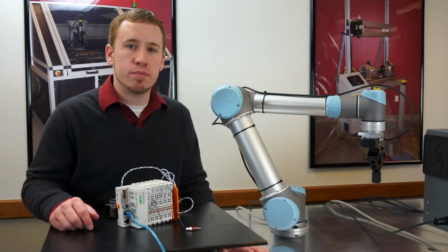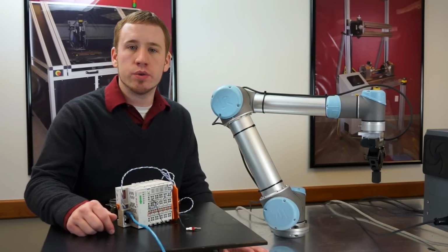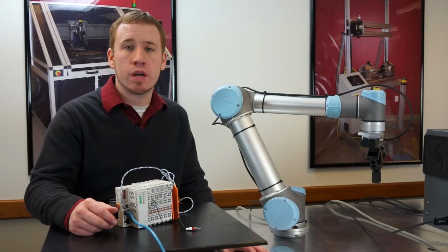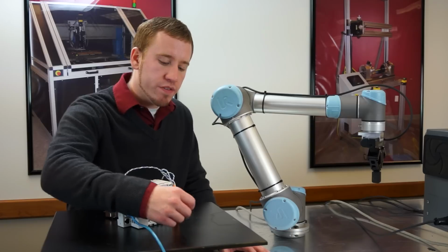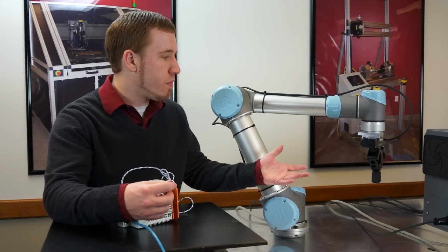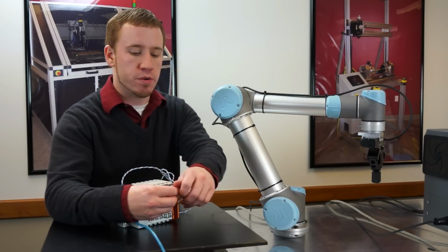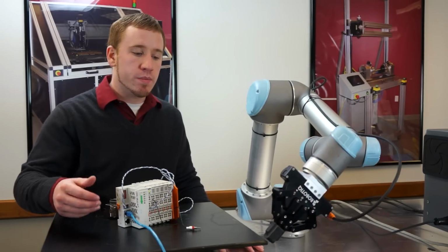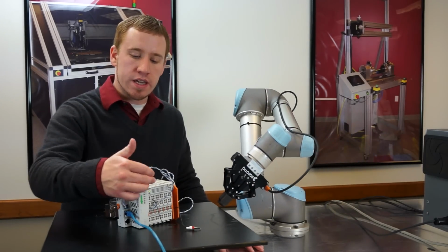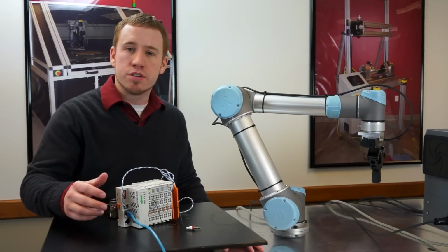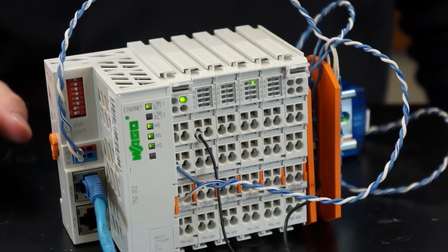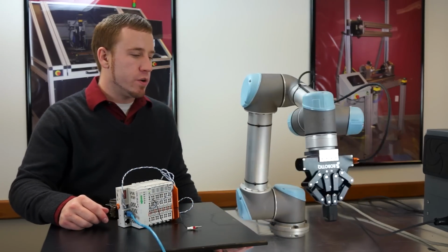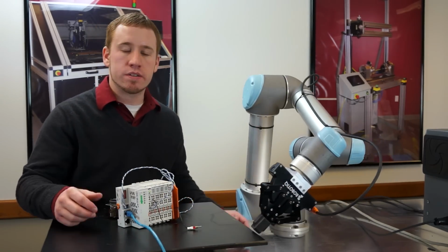Now that we've got everything communicating back and forth between the Wago unit and the robot controller, we can go ahead and test out a program that I created where we're going to wait for this input to turn on before the robot actually starts running the program. So if I go ahead and toggle that input, you can see the robot goes ahead and moves, and when it finishes, I've had it set an output on the Wago unit as well, just to verify that everything's working here. You can see it's on now, and if I go ahead and toggle that again, the robot will move. It's just nice to see everything's connected and communicating.